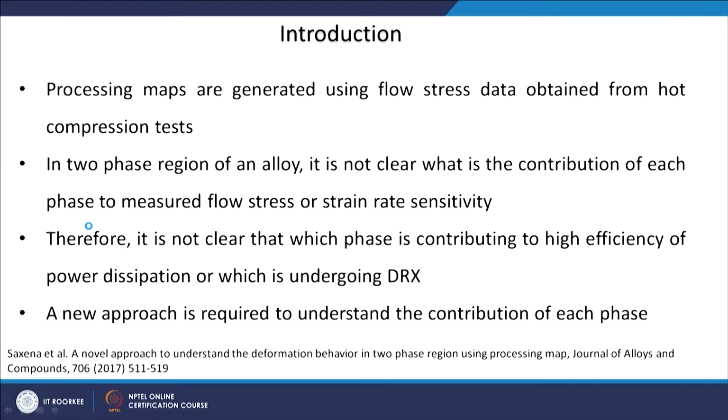And knowing that these phases will deform in very different fashion, as we said in the case of the constitutive equation also, developing one single constitutive equation is not an accurate or good idea for the whole temperature range, because different phases are stable or in equilibrium at different temperatures. So, we propose that information about phase should always be there in the development of the constitutive equation as well as the processing map.